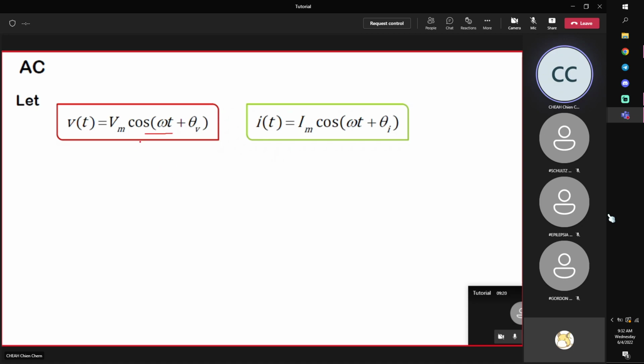sources, with certain frequencies. As I mentioned, in order to use phasor analysis, all the sources, if more than one, must have the same frequency, right? If not, you need to use the principle of superposition. For a linear circuit, suppose that you have an AC source, your signals will have the same frequency, however, there will be a phase difference between each of the signals, and the amplitude will also be different.